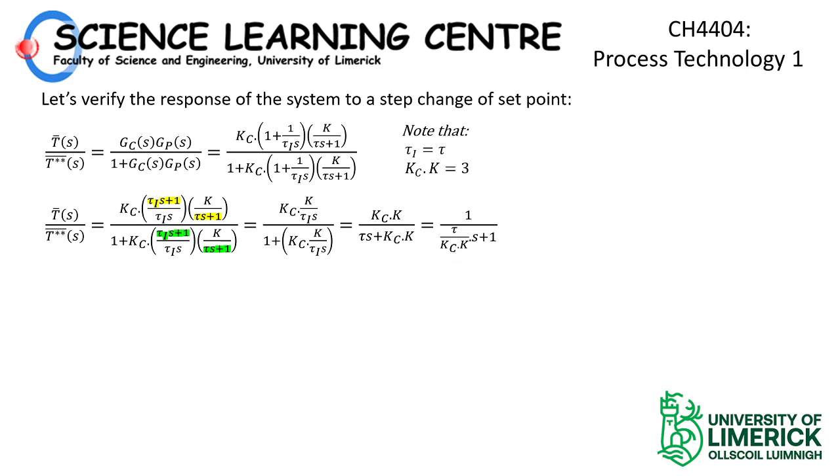What does it mean that we have a K of 1? It means that one unit change of our step function would result eventually in 1 unit change in our output. So if I change the set point by 1 degree Celsius, I expect the final steady state output to change by 1 degree Celsius. It's expected to work that way, right? If you increase the set point by 1 degree Celsius, you expect the temperature eventually of the house to go up by 1 degree Celsius.